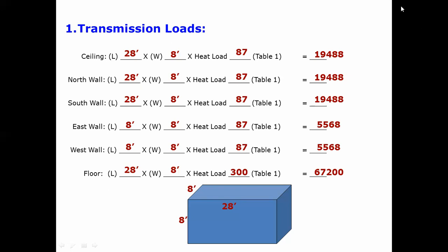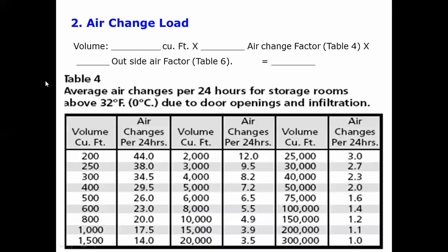Okay, I believe you have written this. Now, second one, air change load. First one was transmission load. Second one, air change load. So air change load means volume in feet cube into air change factor into outside air factor. Okay, this is the air change load formula.